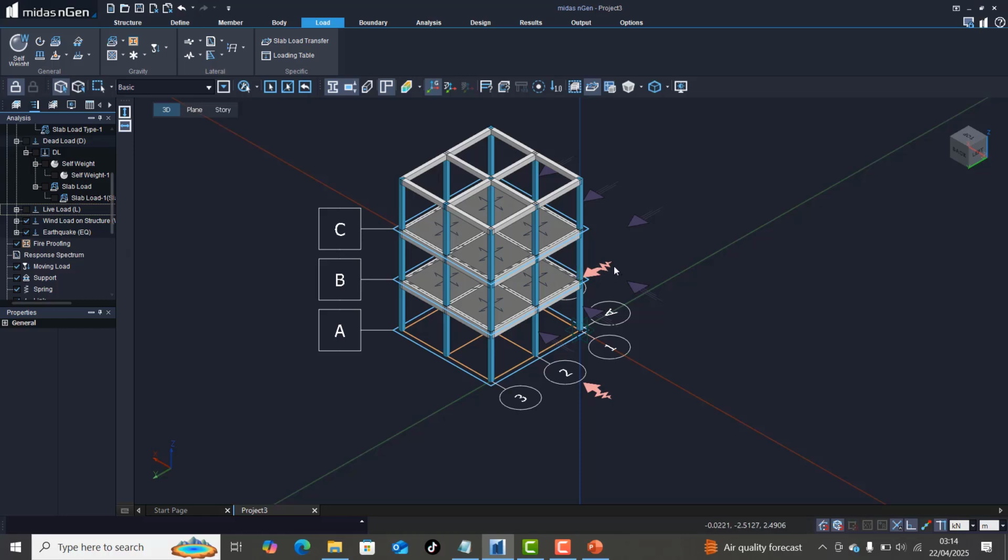So you can see I have my load along the X direction and also along my Y direction. I can check for this under this is my earthquake load actually. So you can see that is already existing. My seismic load is on my project. Alright, so on this video I have been able to cover extensively from the self weights to the slab load to the wind load, and then we went down to seismic load.